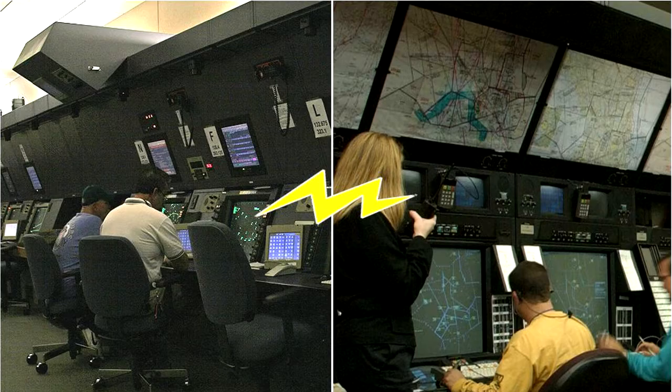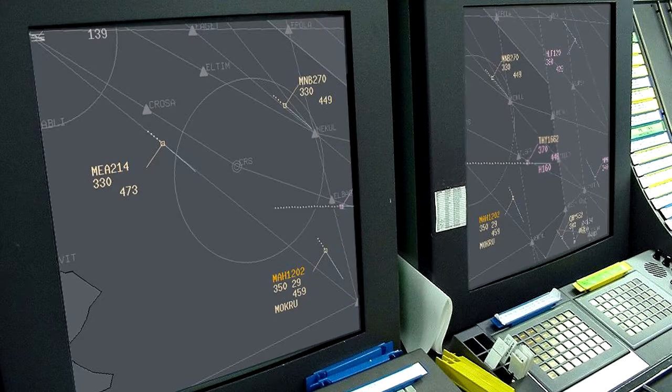A number of times throughout this lesson, it has been stated that it is possible to transfer a radar identification from one controller to another. However, it is important at the outset to understand that the transfer of radar identification from one radar controller to another should only be attempted when it is considered that the aircraft is within the accepting controller's radar effective range.